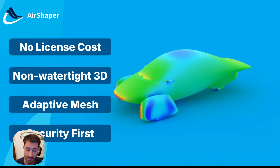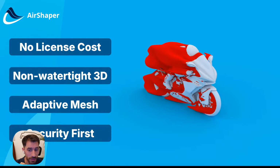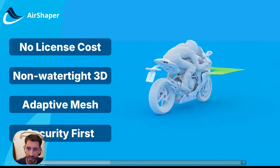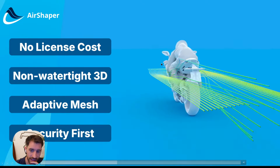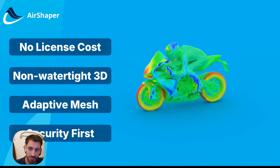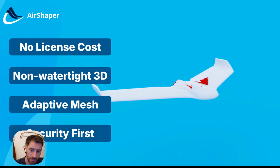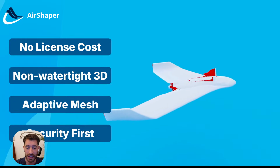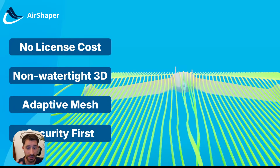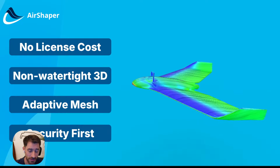We will analyze the gradient of the pressure, the vorticity in the flow, and then refine the mesh locally where it's most relevant for your flow, in the wake for example, that you see here in turbulent areas and so on, and make the best possible use of the cell budget that we have available for your simulation. So when we talk about a 10 million cell mesh, it's usually the equivalent of maybe 20, 25 million cells that you would generate manually using conventional techniques without adaptive mesh refinement.